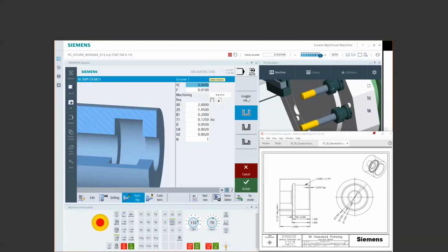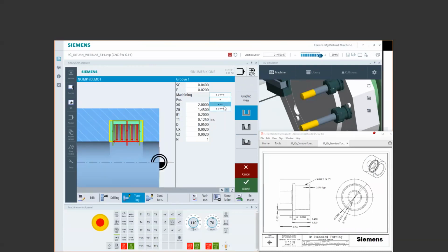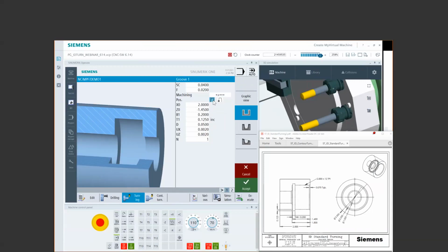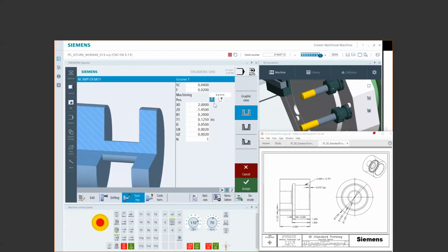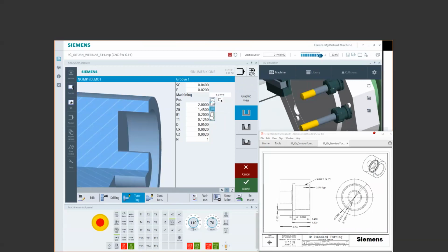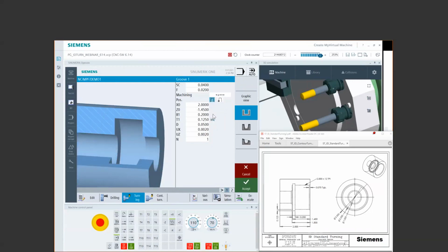Now, when you set up the grooving cycle, just like when you set it up on an OD, I have to give it my safeties and my feeds. Tell it, am I roughing, am I finishing, or am I going to rough and finish all with the same tool? Maybe I'll do it all with the same tool. Now, this lower first icon is going to define whether it's an OD, face, or an ID groove.